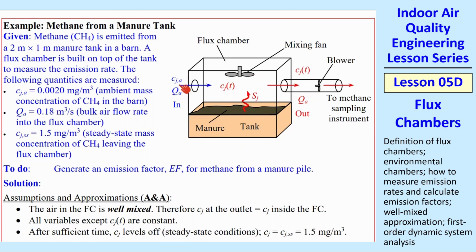And we do the same thing we did in the example when I was deriving this. We have ambient air coming in, Q_A. We have Q_A going out. We measure methane concentration, and have a blower that sucks everything through here. And the manure, if you've ever been around manure, it stinks, right? Well, part of the gases that evaporate off of this manure surface is the methane, CH4. So here are the quantities that we measure. This tank is 2 meters by 1 meter. C_J,A is 0.02 milligram per meter cubed. That's the ambient, so there's some ambient in the barn there.